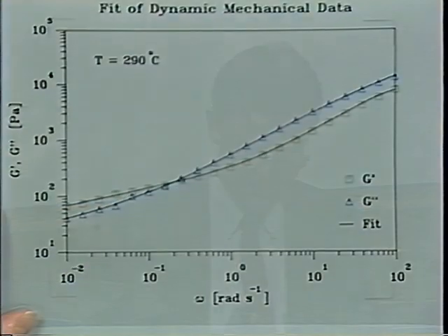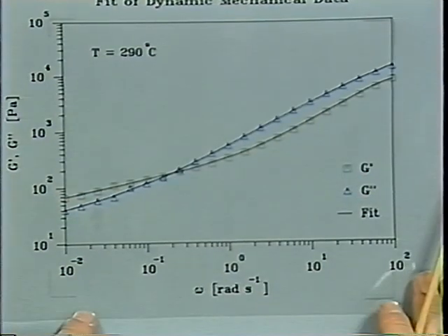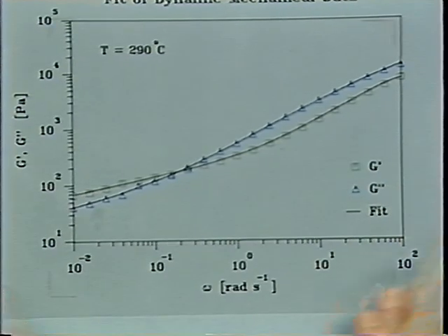There certainly is a linear viscoelastic range, as you saw, and within that, we can determine G prime, G double prime in its full extent. You see typical data here, but you also see that at low frequencies, there's no terminal region. If we had reached the terminal behavior, G prime would have a slope of 2 or a slope of 0, depending on being a solid or liquid. Solid would have slope 0, and slope 2 would be for liquid. So with this data, we don't even know whether it is a liquid or a solid. It's behaving in between, but that's no excuse.